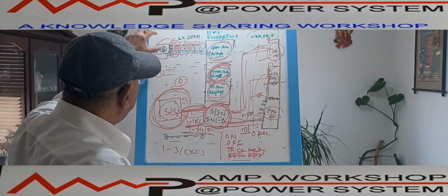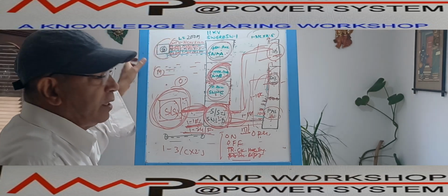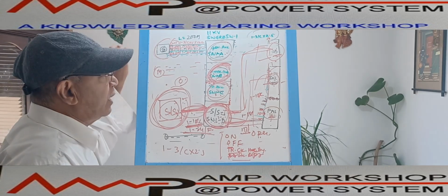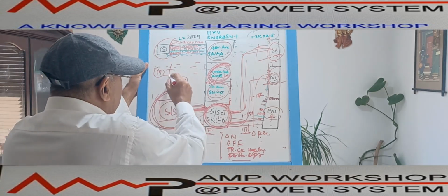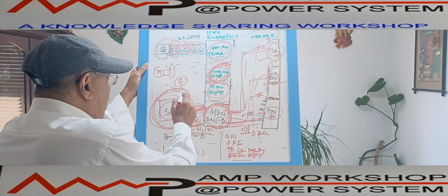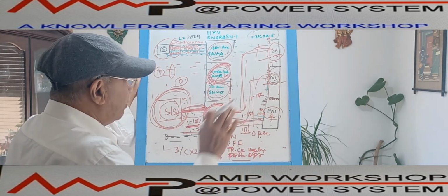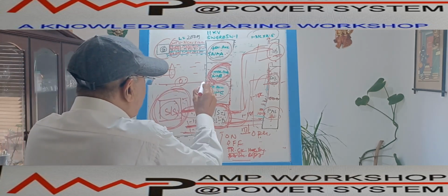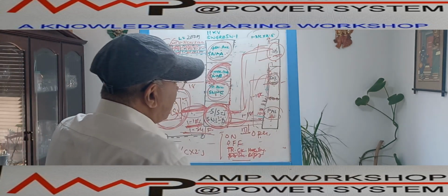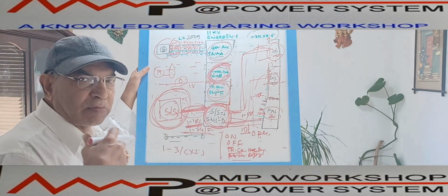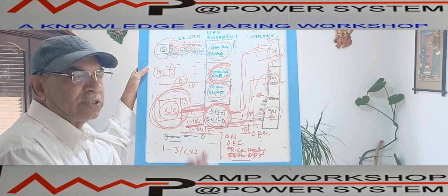So this way, if we calculate for one generator, then if we have multiple generators, we can estimate how much cable is the requirement. Similarly, if we calculate for one motor, if there are multiple motors, we can multiply in this way. Similarly, for how many substations we are supplying, we can calculate in the same way. In the case of a transformer, how many cables? In the transformer, there is one common 18 core cable, and here there will be four cables. So for one transformer, if I calculate this cable, then how many transformer feeders we have? Based on that, we can estimate the cable.